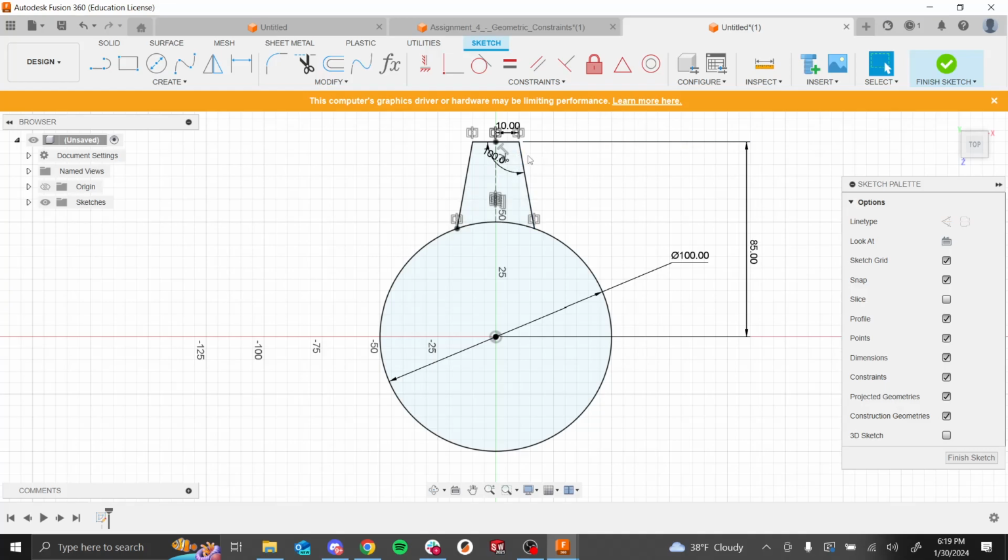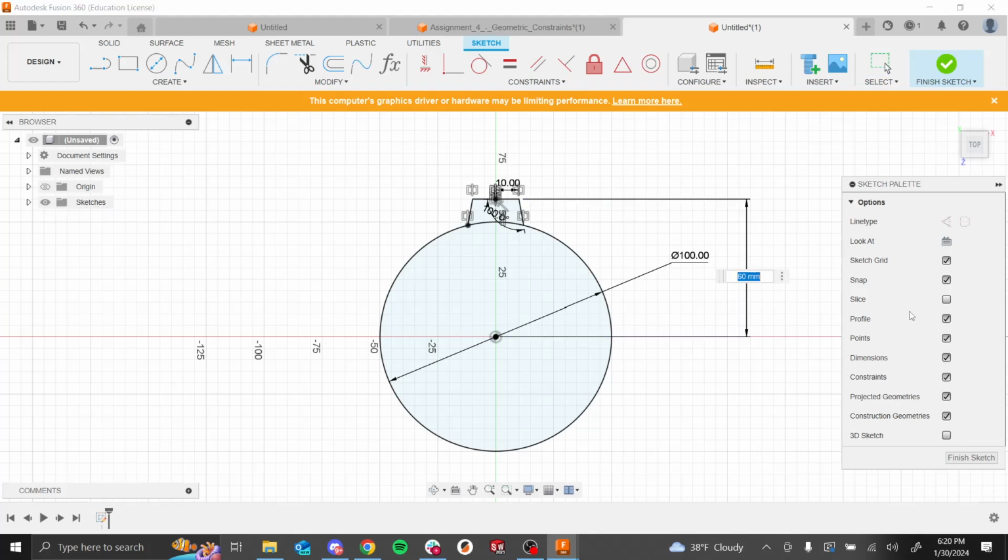So now that we have one full tooth, we're gonna create a bunch of them, right? And the nice thing right now is that if I change the tooth, the mirrored image of it will also change, right? So if I change this from 85 to like 60, this tooth is like smaller now, which is nice. I'm gonna change it to like 70. All right.